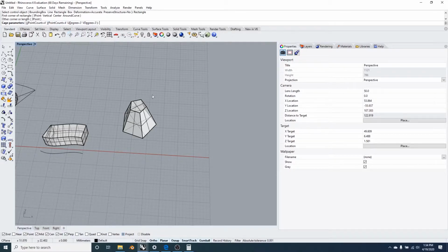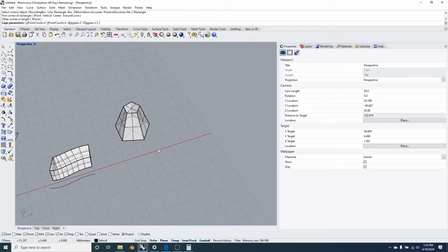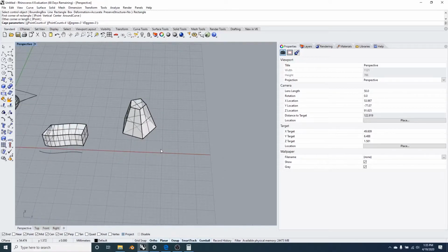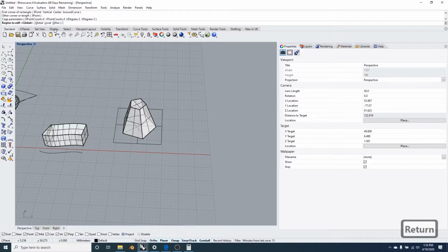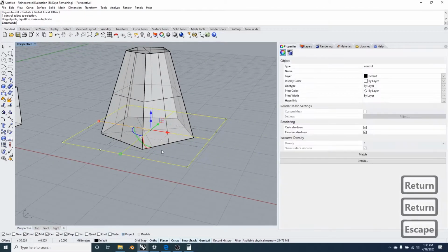So pretty much surfaces get their own set of coordinates. U would be X and V would be Y. So it's the same concept. So X points would be 4 and Y points would be 4. So I would get a 4x4 grid. I'm going to hit enter. Enter one more time, and then you can see that I got all those points in there.